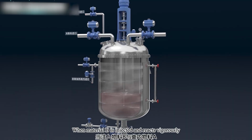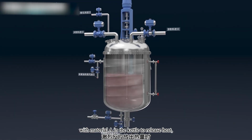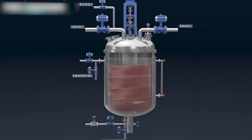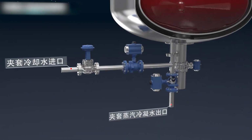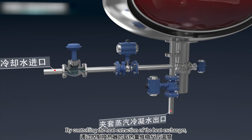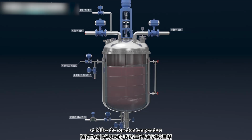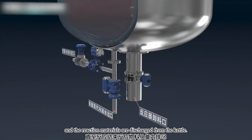When material B is injected and reacts vigorously with material A in the kettle to release heat, replace the high-temperature steam in the jacket heat exchanger with cooling water. By controlling the heat extraction of the heat exchanger, stabilize the reaction temperature until the reaction ends and the reaction materials are discharged from the kettle.